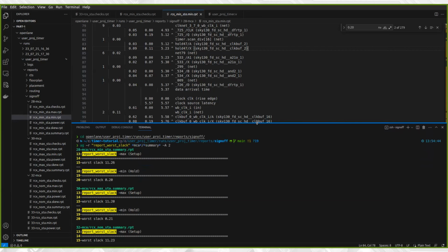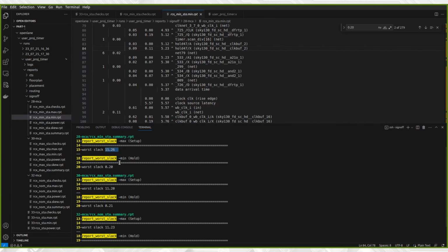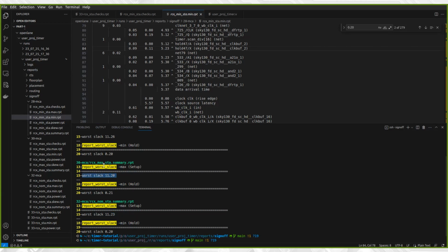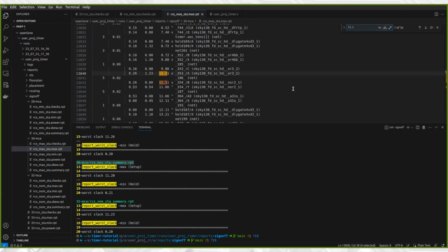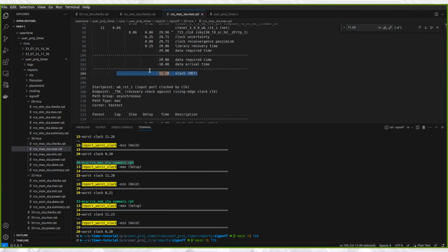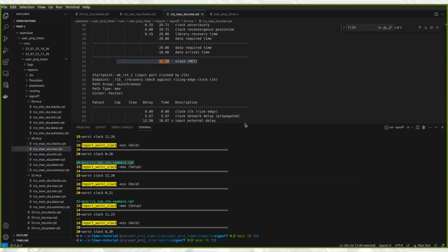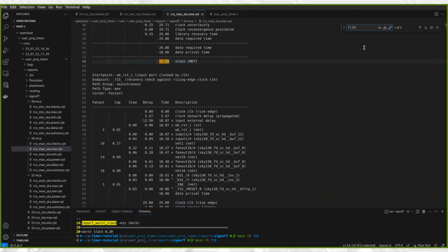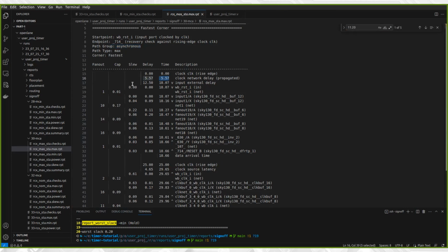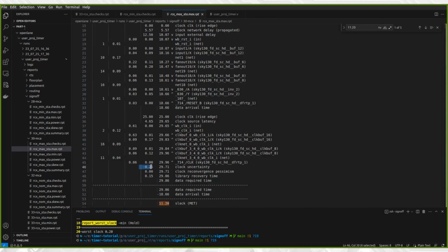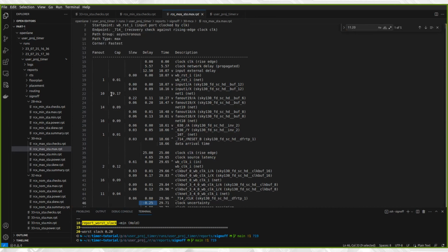For the setup slack, the minimum is plus 11.20 nanoseconds at the max corner. Then go to the 30-MCA/RCX_max_STA.max.rpt file and look for the minimum slack to determine the PVT corner. The critical path is reported at the fast max corner. From the path it is verified that the clock is propagated and the reset input delay is set. As well, the setup slack is considerable, which allows operating at a faster clock of a period of as low as 15 nanoseconds.